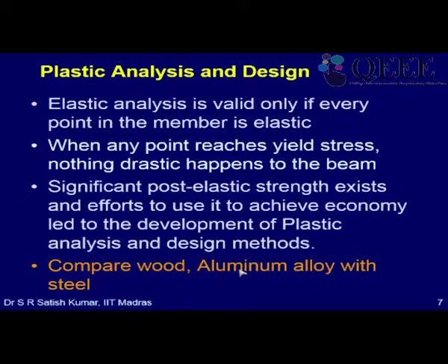So in such cases, again, we may not be able to use plastic analysis because within the elastic limit itself we are having problems, and it's the deflection which is governing. Again, in such instances, for example, even if it's a steel beam, if it's a very long span beam with a very low intensity of load, then it may be governed by the deflection limit. So in such cases, we will not have any advantage in going for plastic analysis.